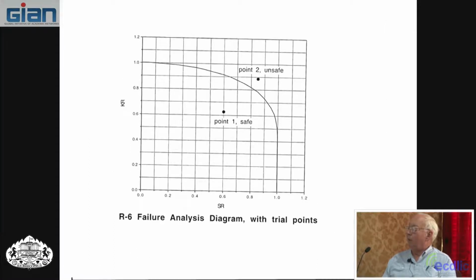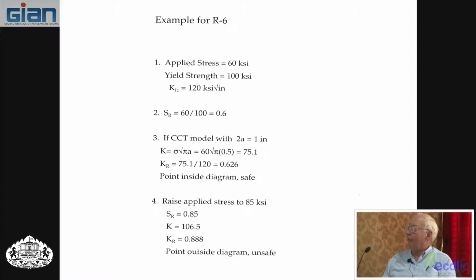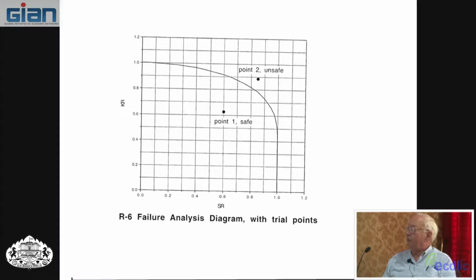So stress ratio 0.6, K ratio 0.626 puts it well inside the curve.